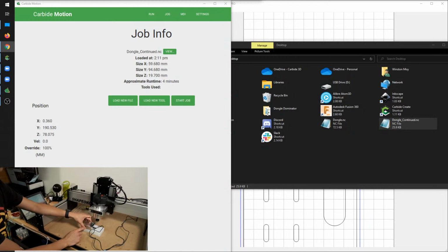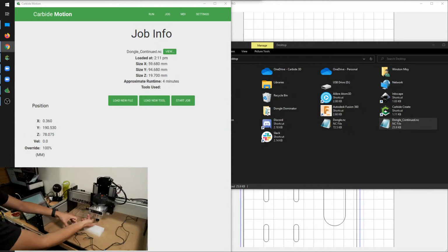And so once you lose that reference position, the only way you're going to be able to recalibrate or adjust for a new tool length is either you reference something fixed, like the wasteboard, or you use a tool setter.